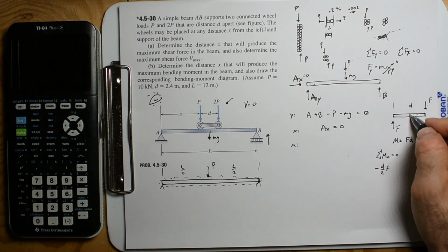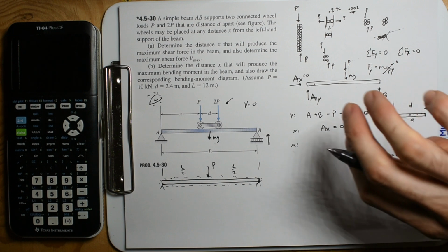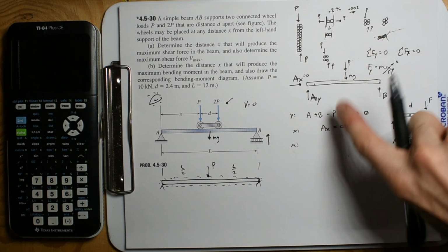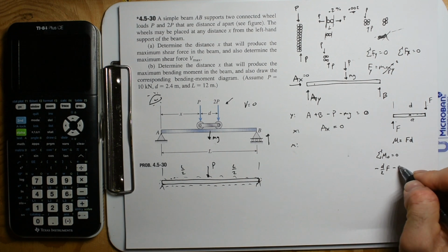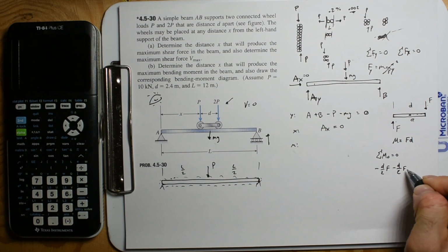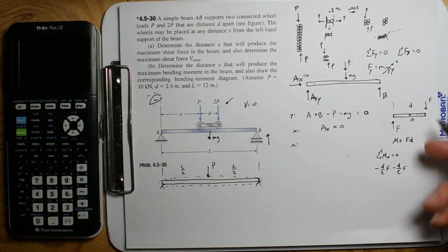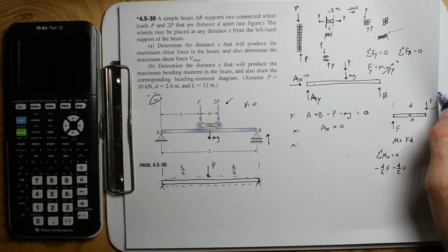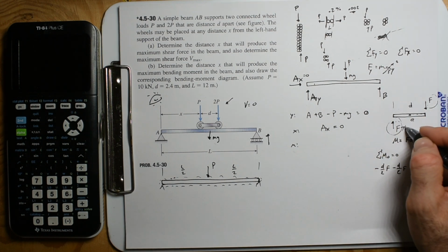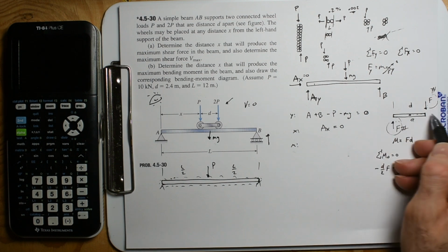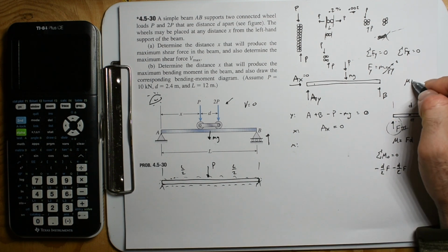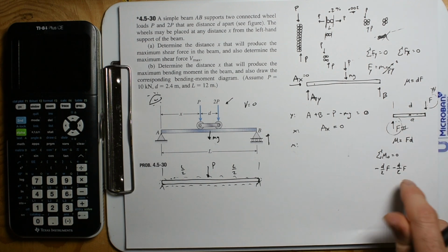Now let's do this force. From this point, that's going to also cause it to spin. My thumb is down. It's going to cause it to spin in the negative direction. So we also have negative d divided by 2 times F. And I always do this because I swear this is the definition of a couple, where you have the same magnitude on both sides separated by a distance. And this is the definition of a couple, where the moment of a couple is just d times F. And so that's what we're seeing right here.